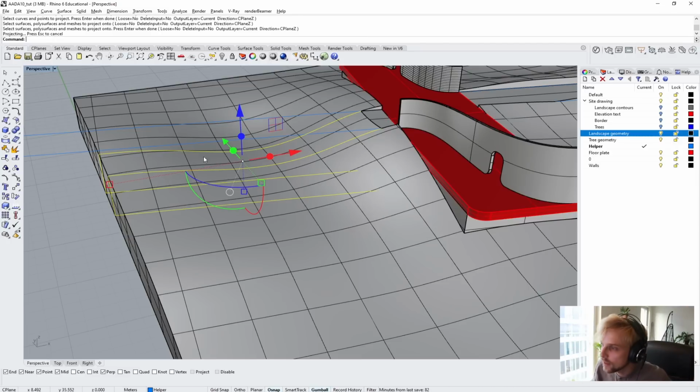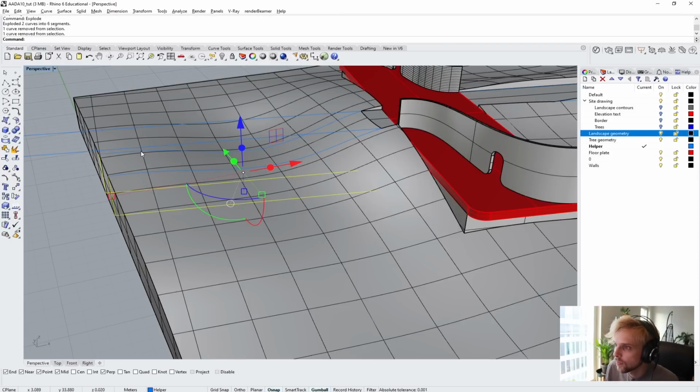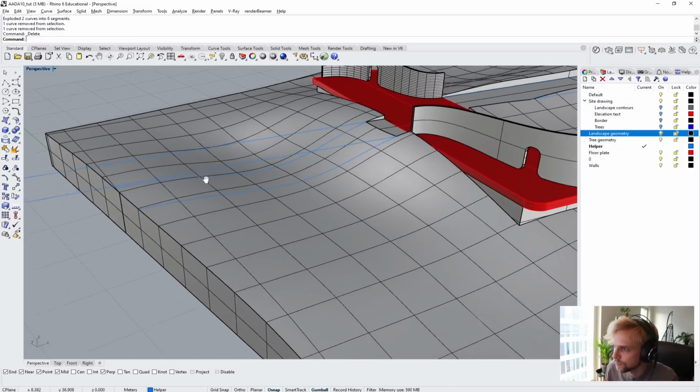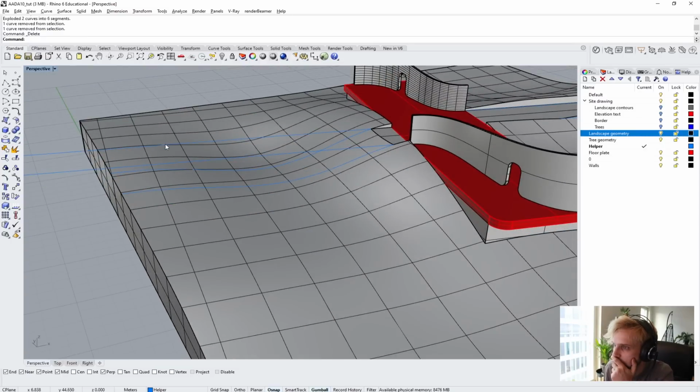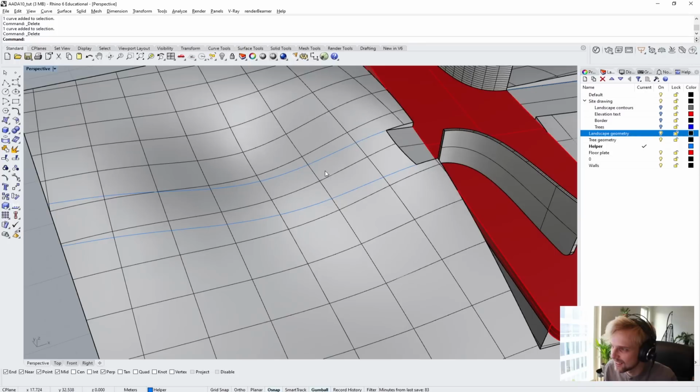And if they hit it twice, then it's going to create two sets of lines. That's fine. I have this selected. So then I will press explode or type in explode. And I will just unselect the top ones, the ones that I want to keep. And I will delete the other ones, the two other ones, right? So I have that done, and now I can actually get rid of the straight ones here because I have the squiggly lines done here.